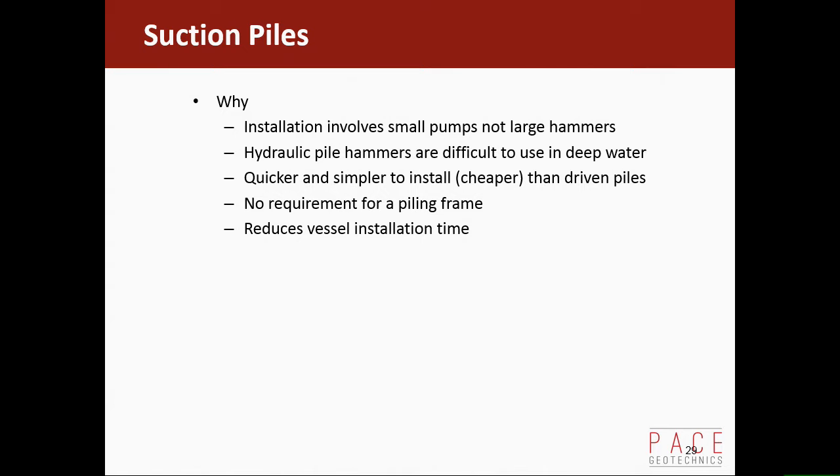So they're quicker and often simpler to install. When you land them on the seabed, they sink in enough under self-weight to be stable. Not like a driven pile where you might have to use one of those frames I showed before. And that all reduces your vessel installation time as well. It's probably the biggest cost.